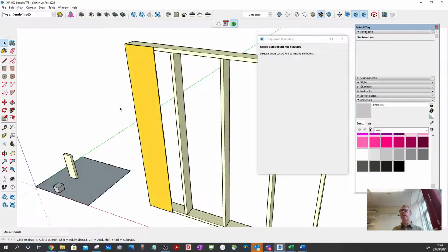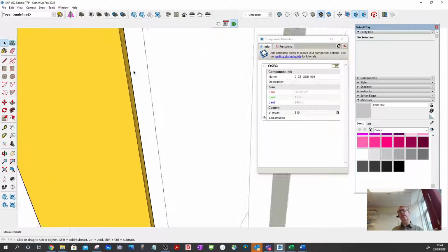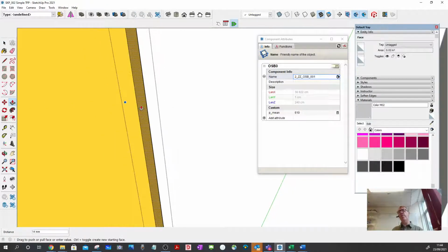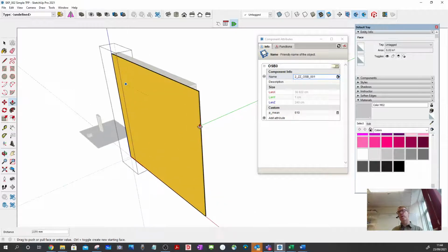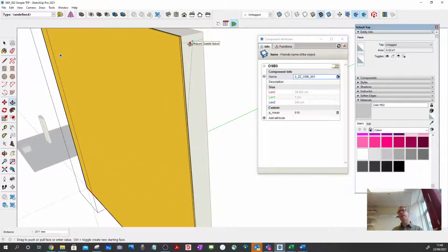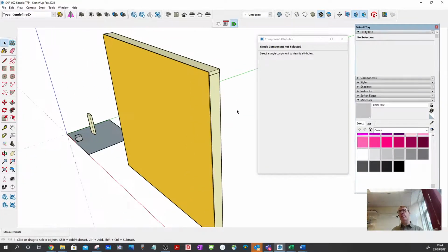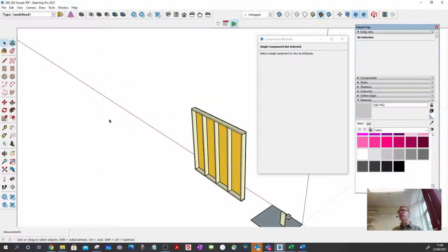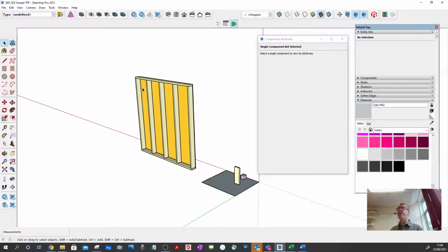And then here, double click, select this face, and pull it out until it hits this surface here. Snap. Click out of everything, deselect it all. We're starting to see the timber frame complete. Well, it's not quite complete yet.